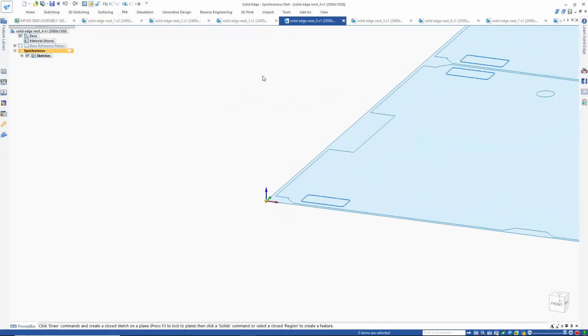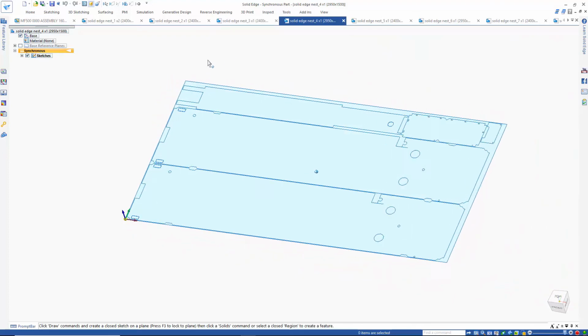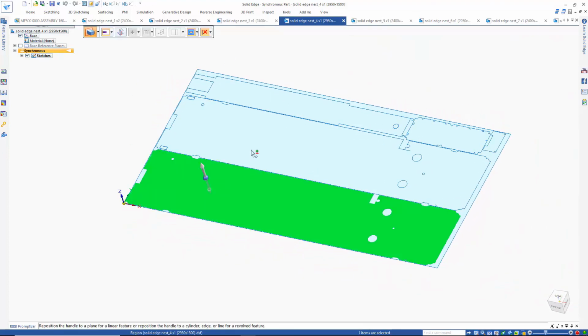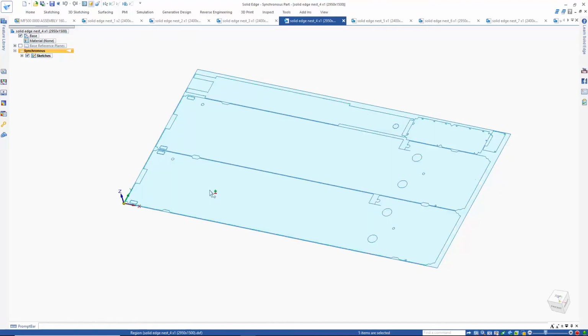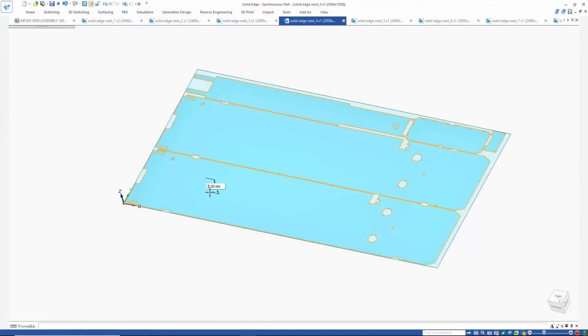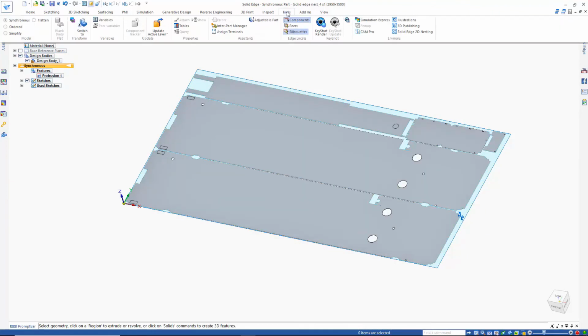Now we can continue our manufacturing workflow by cutting out these shapes on our water jet machine. First, we can extrude these 2D shapes back into physical objects. Solid Edge with synchronous technology makes this job easy. We'll extrude them for a distance of 2 millimeters. Great. Now we're ready to send them to Solid Edge CAM Pro.